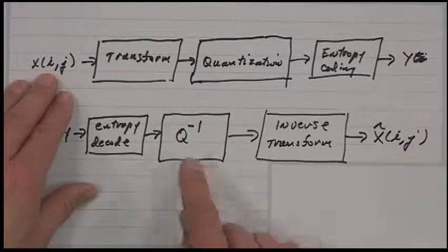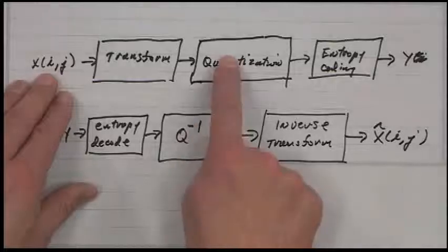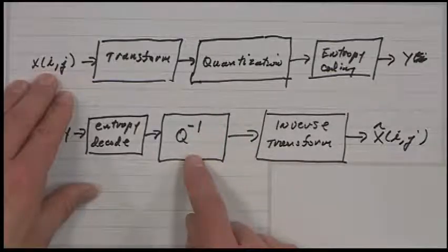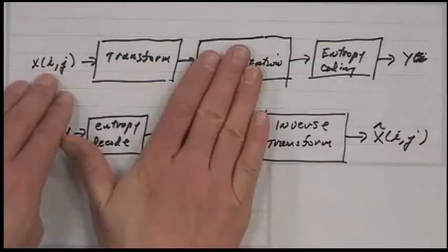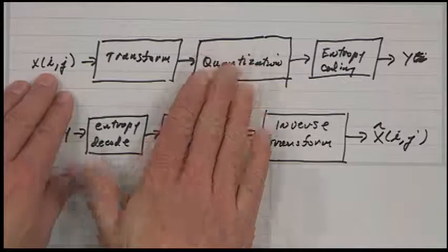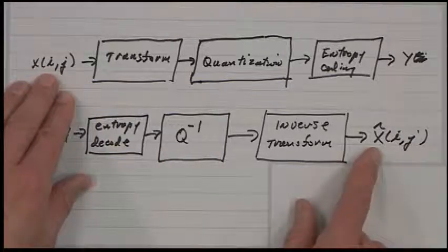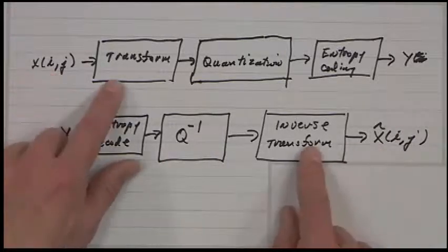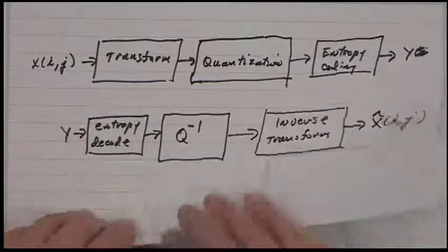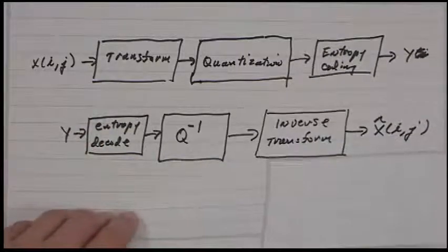And in lossy, you have quantization that occurs here. Nearly lossless usually means that you did no quantization, but you got something that still wasn't exactly bit for bit the same. It was just very close because the transforms are not exactly matched numerically by the computer in floating point precision.